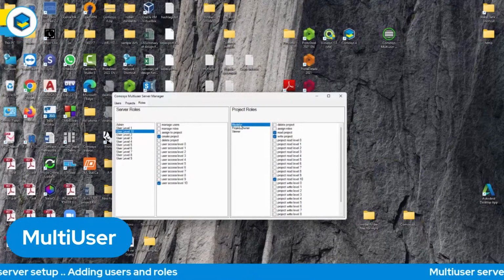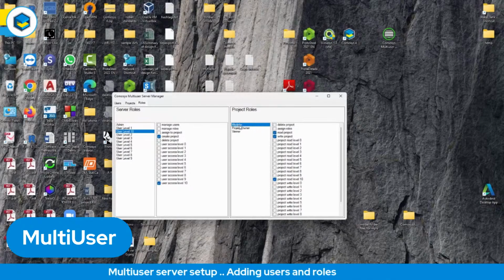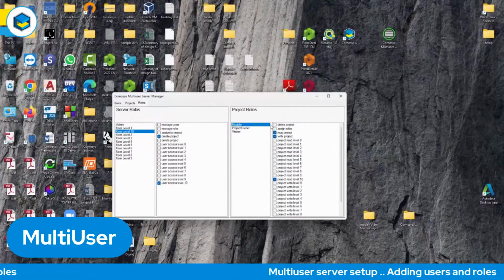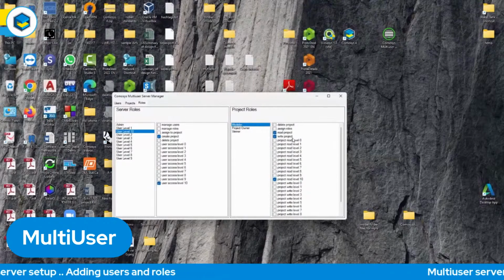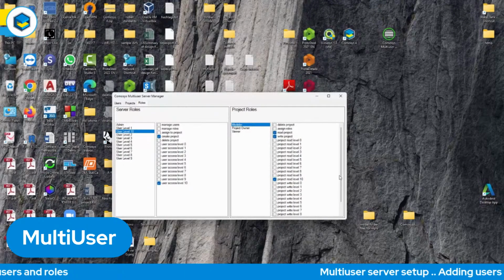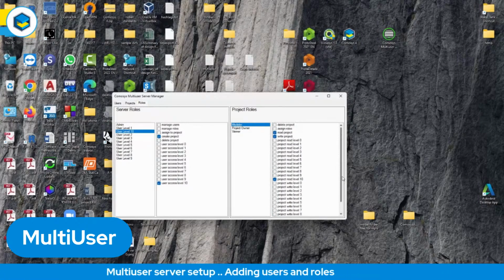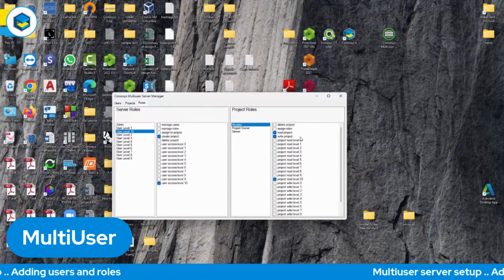Now, when it comes to the modeler, the modeler is someone who's participating in the modeling. So there, like I said, 5 people on the same model. The modeler is also working, but this modeler cannot delete the project. So according to these rules right now, only the owner can delete the project, but the modeler has not been given the right to delete the project or to assign roles to other modelers or other people on the project. But he can read the project, he can write on the project, and he has a read access level of 10 as well as a write access level of 10. So basically he can work on the project just like the owner can, but he cannot delete or add more users and assign roles to that project.